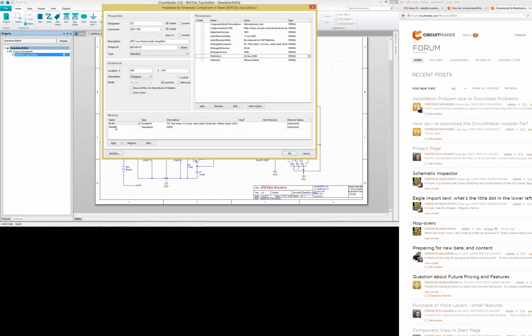Models. Essentially, the anatomy of a component in Altium land is it has a schematic symbol, it has parametric data, and the schematic symbol ultimately, when you place the part, becomes the glue that holds everything else together, including SPICE simulation models and PCB footprints. And within the footprint, we may have a three-dimensional mechanical model as well.